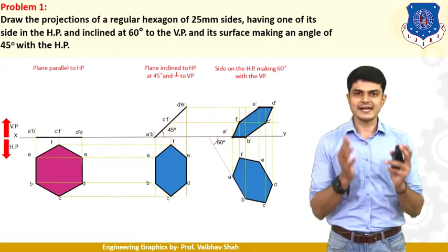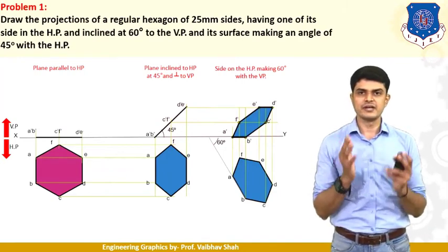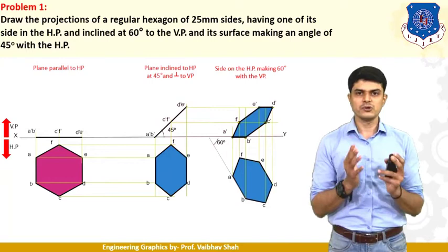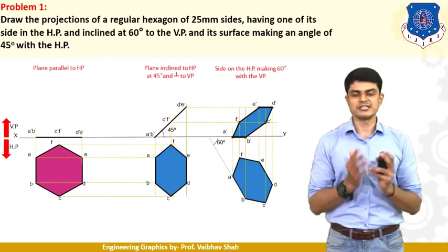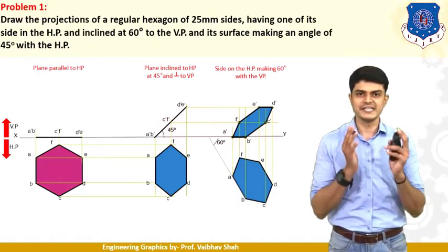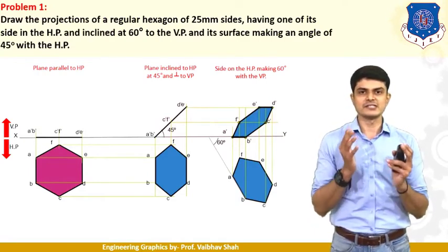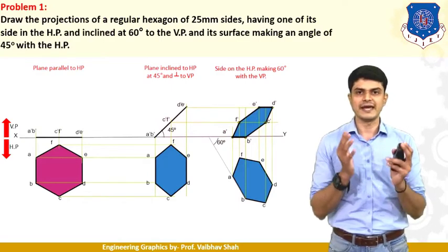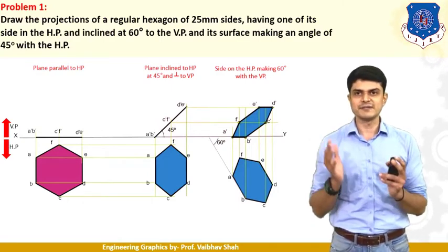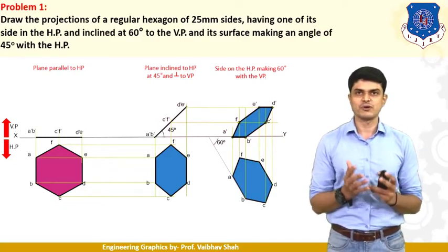When you connect these 6 points, you will have this hexagon like I have drawn. After getting this hexagon, let us give the numbering pattern A, B, C, D, E, F in the anti-clockwise direction. So our true shape is drawn in HP. After getting this true shape drawn, we should draw vertical lines from each and every point of your hexagon, and we will be having one horizontal line as a front view in VP on the XY line, as you can see. So A dash, B dash, C dash, F dash, and D dash, E dash. Then after, in the next stage, what is said?